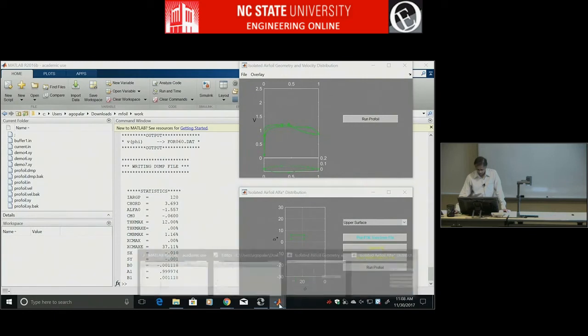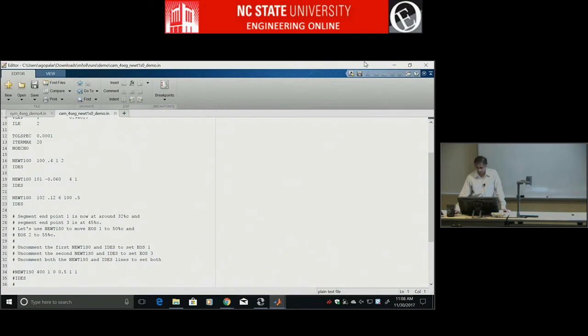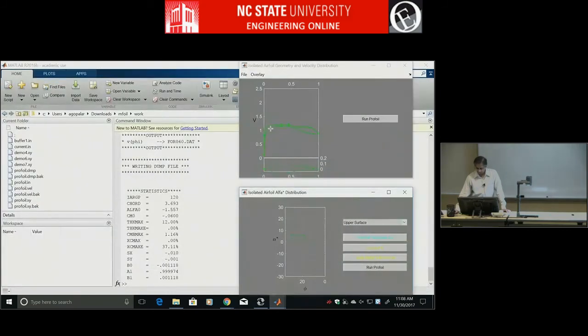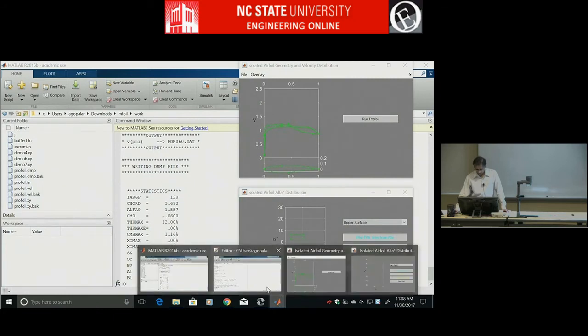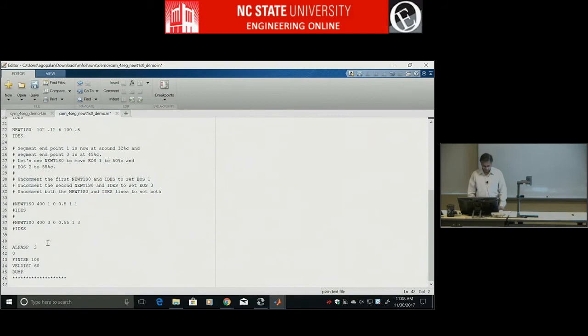at 2 conditions. I don't know what the conditions are. It's like 0 and 2 degrees. So the inner 2 velocity distributions are for 0, upper and lower surface, and the outer 2 are for 2 degrees. Just kind of looks a little weird because they all cross over. Maybe just to get some clarity, let's make it as 1. Let's just do 0 degrees.